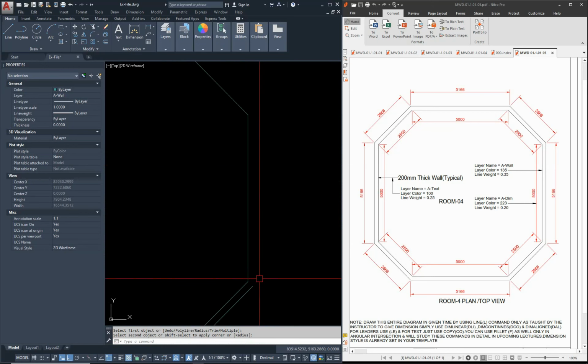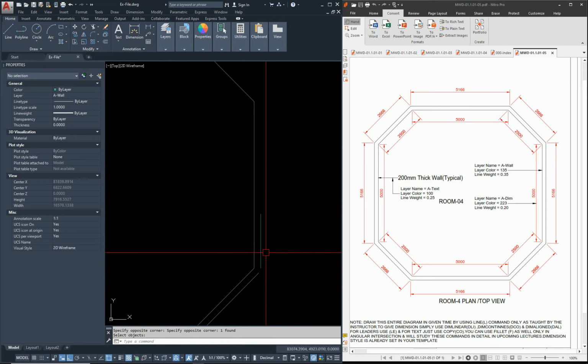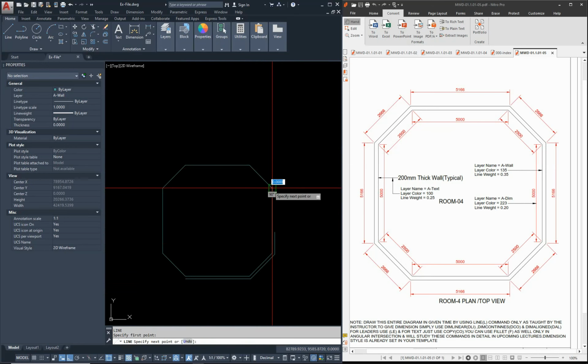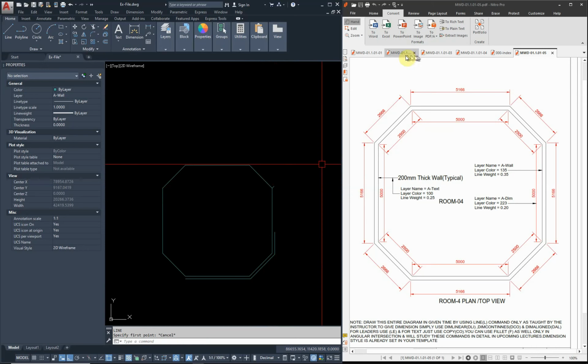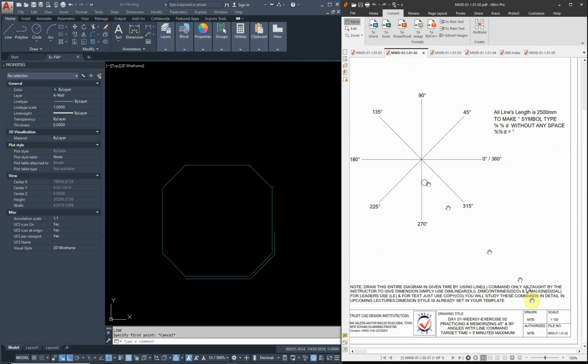We all know the fillet command very well right now. I will draw a line 200 mm and just a slight line. No need to draw the entire line because fillet will match these two points. Fillet, select first point, second point, and that's it. Now again I will draw this line shift at the rate 200, and my angle is going in the 45-degree direction. And again, see, you have to practice this exercise very well, the exercise number 2.